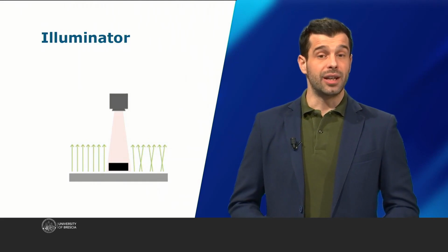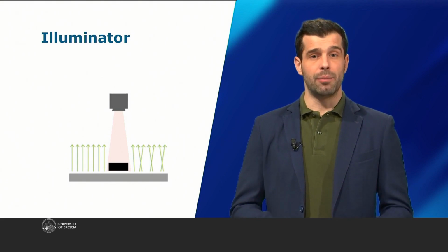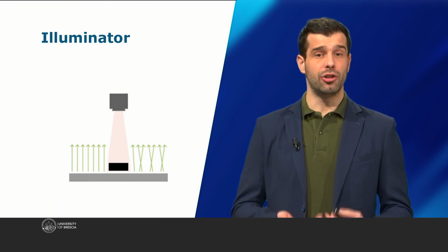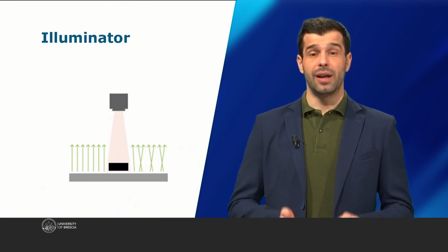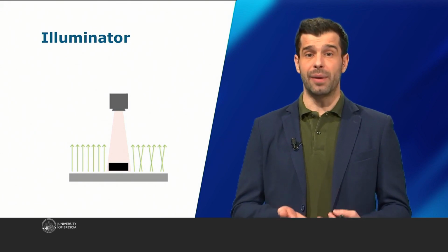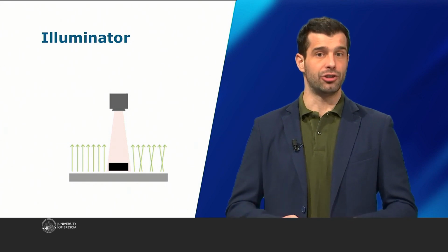Finally, let's define the illuminator. Since I need to measure a diameter and not, for example, read an inscription engraved on the ring, it's perfectly fine to use a backlight type illuminator, which allows us to see the edges of the object very clearly. And to make sure that these are highly contrasted against the background on which the object is placed.